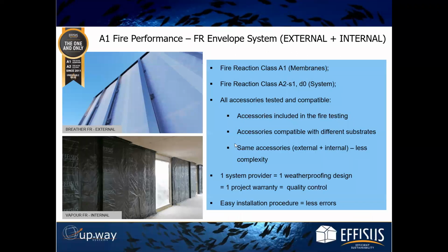Also, I believe it is important to share with you that A1 fire classification is the best possible classification that we can achieve in terms of fire rating. We have done so in the membranes, but we also needed to simulate the end use on a facade. When we are applying these membranes, we do need adhesives, tapes, sealants, and all of that needed to be tested in order to understand exactly how everything would behave if exposed to fire. When we did this additional test, what we got is A2-s1,d0 for the whole system. So we are also very confident of our solution as a whole.